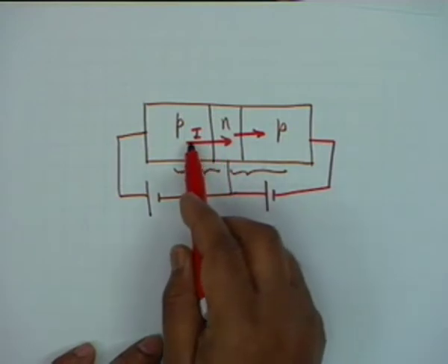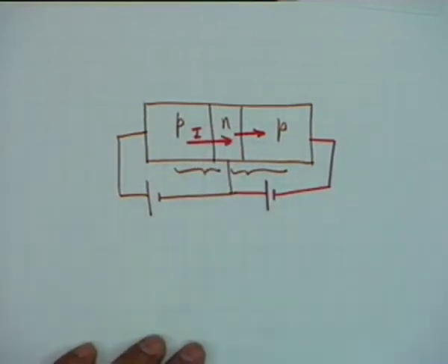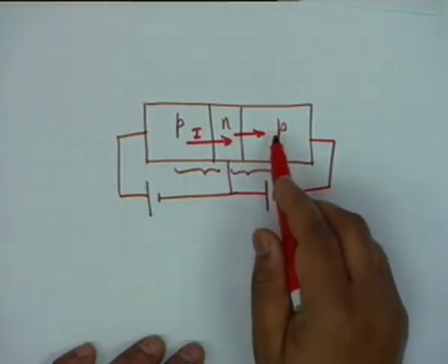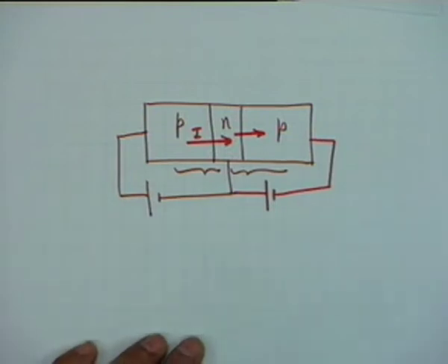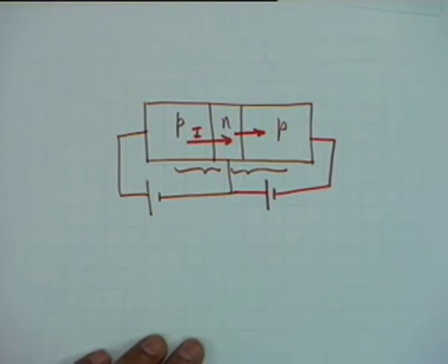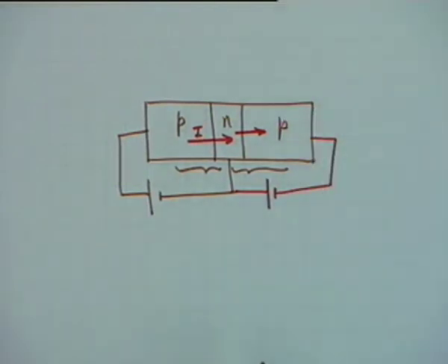Now the current that passes through a small resistance in this p-n junction, if this same current is forced to pass through the high resistance of a reverse bias junction, then obviously we have achieved our purpose. That is, we have transferred a low resistance into a high resistance and therefore this will act as a transistor, and that is the basic reason why a transistor can amplify.